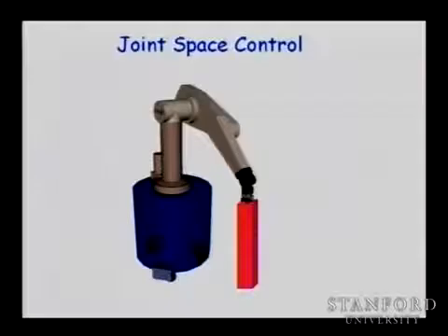And if you do that, actually, you lose a lot of inertial properties that you can use in the control of the robot, as we will see a little bit now and much more later when we analyze the fact that this base is heavy, this arm is lighter, and if you are able to use this fact of macro structure and mini structure and combine them, you are going to be able to better use the reduced effective inertias that are coming from macro mini structures and controlling the robot in a much better way.